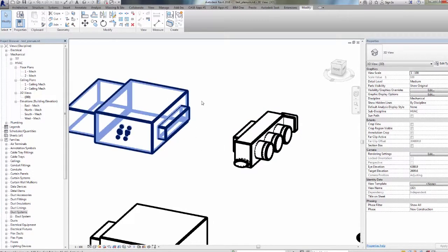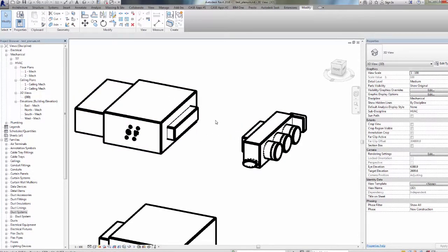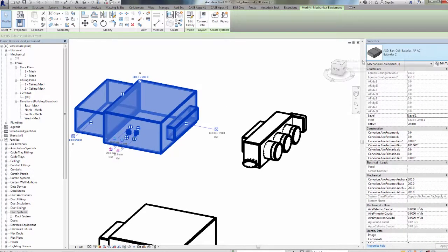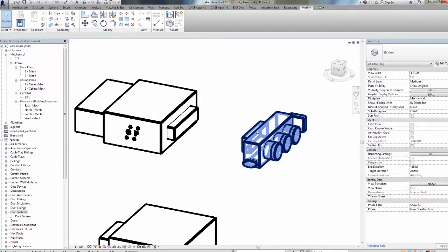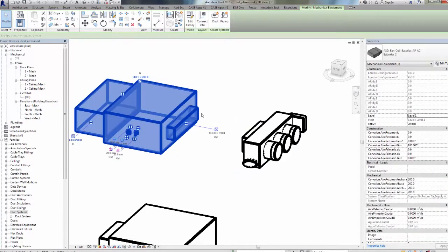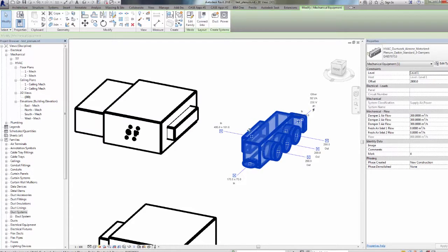A good practice, if the neck dimensions are being changed, could be to change the name of the type, specifying that these are being modified for a concrete indoor unit. Having this indoor unit, let's say it's a Daikin, we are now creating for this plenum a new type, assigning the right dimensions to the neck so it can be adjusted to the indoor unit. We see here the dimensions of the indoor unit. These are the real dimensions of the connector, and we see how they do not coincide with those from the plenum.